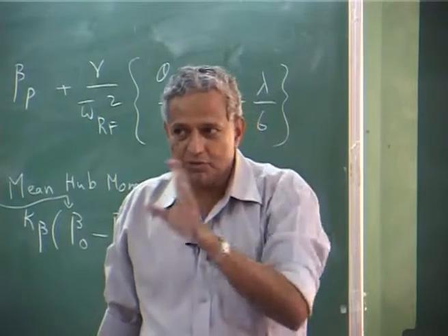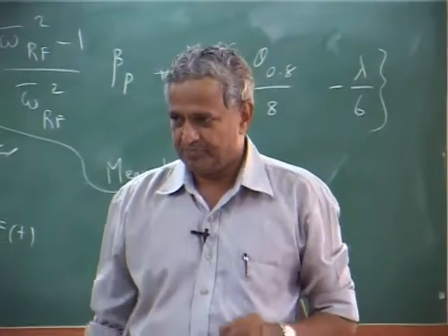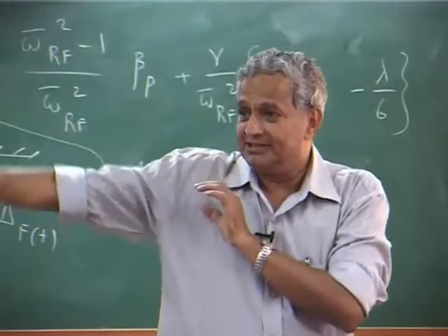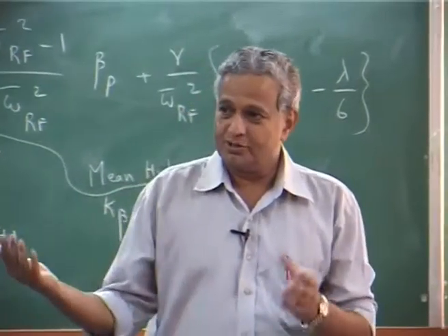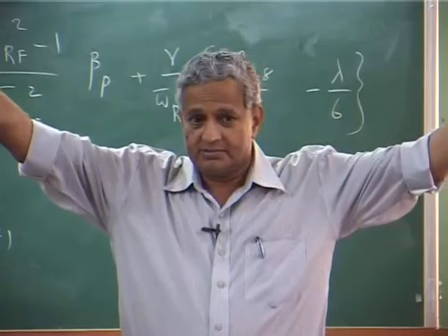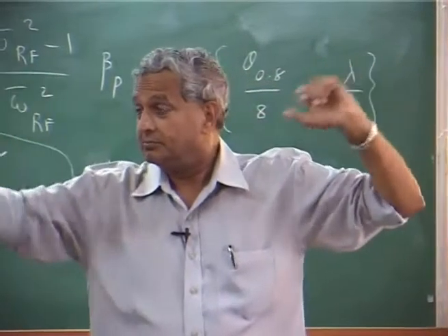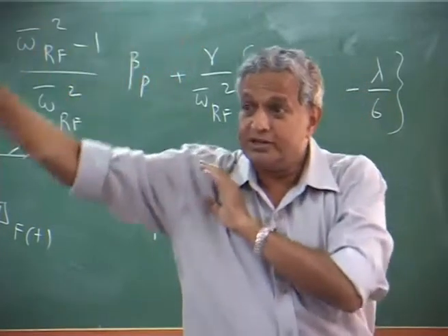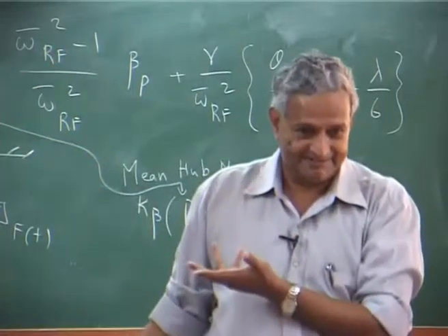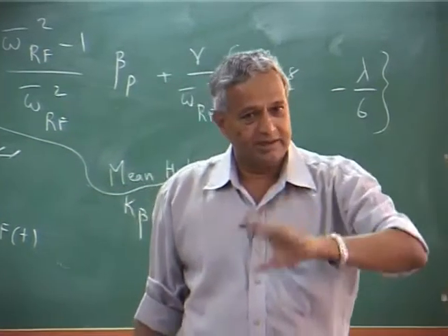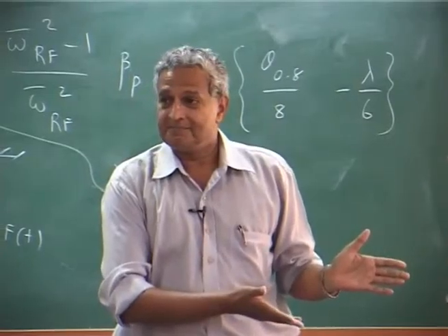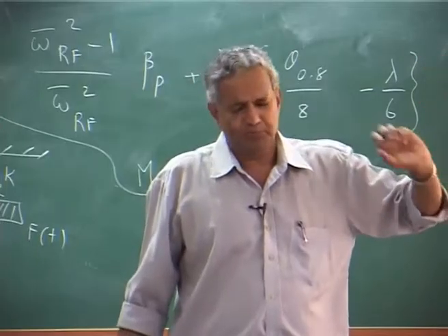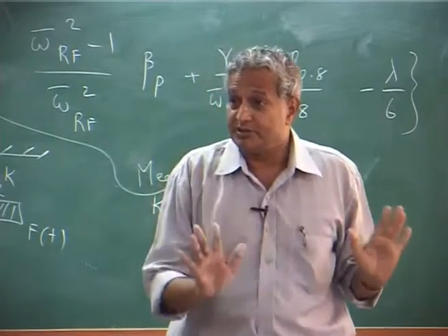So, that is why usually you do not look at flap deformation, because depending on the flight condition, it can come down, it can go up, anything. Because if the coning is too much, that means your lift is very large, that is why it is going up. If the coning is very less, it means my lift is less. So, the coning angle changes with your weight condition, that is why all these are just to give some 2 degrees, you relieve the hub moment. It is purely from a structural design point of view.